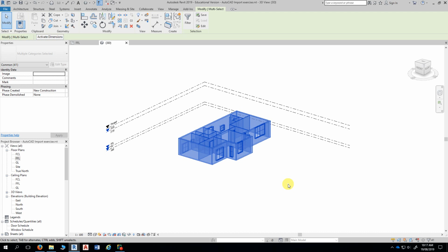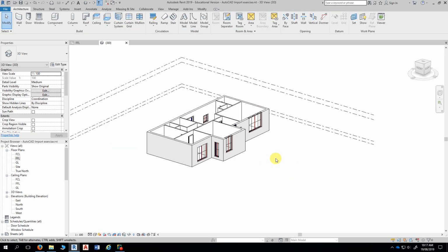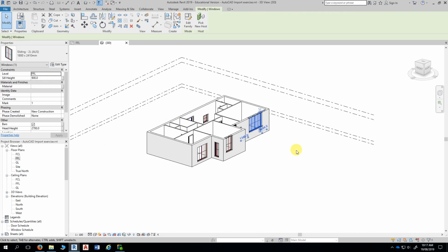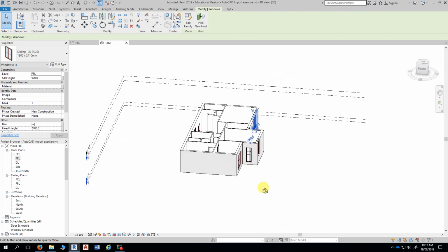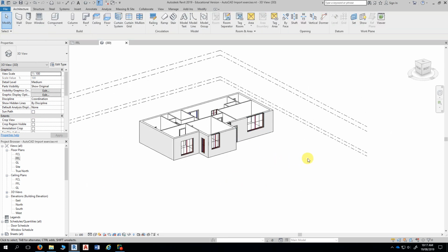Array. Oh, hang on, there's an S thing in there. Select all, SA. There's a shortcut. If you select one of the windows and type SA, it will select all items of that type in the project.